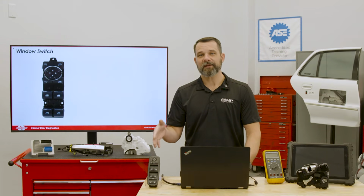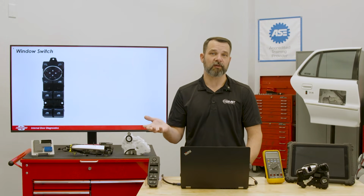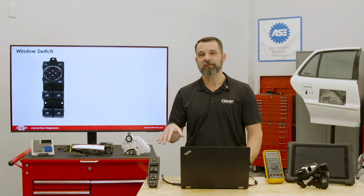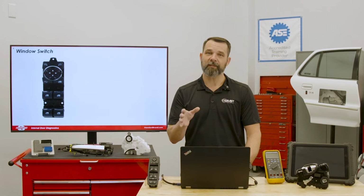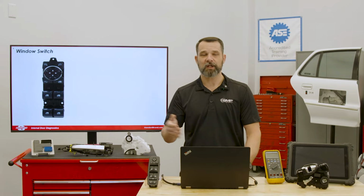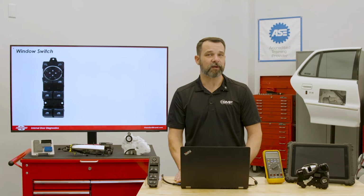All right, so now on to the window switch itself. Let's think about this as the main command center for all the windows and even the door locks most times, power mirrors, and even puddle lamps, depending on the vehicle and the features that it has. Now, these can communicate in different ways. Some are direct wiring to the motors, but those are primarily found on older systems. What we typically see now on newer systems is where they're going to communicate over the network through either the body control module or the door control module. We'll talk about that more here in a minute.